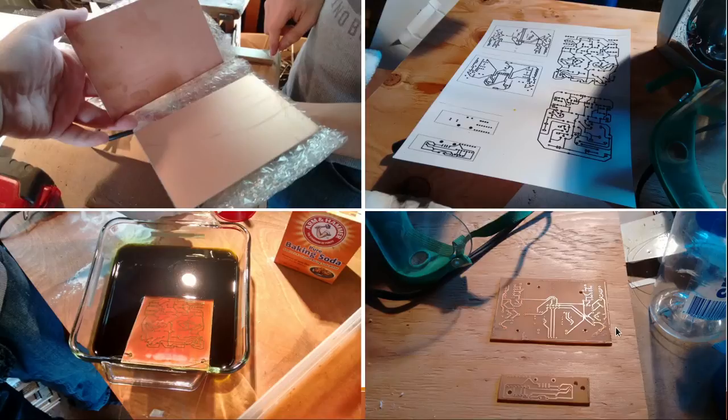This main board I made double-sided, and I was quite impressed that I was able to line the holes up. I didn't fully account for trace width or pad size, so some of the parts covered the pads and made it very difficult to solder. When I first tested it after soldering everything together, it didn't work, so I just abandoned this board and went back to the prototype board, just because I didn't want to put in the effort to debug this board. I did, however, use the power board, which has the microcontroller LED and filter capacitor.